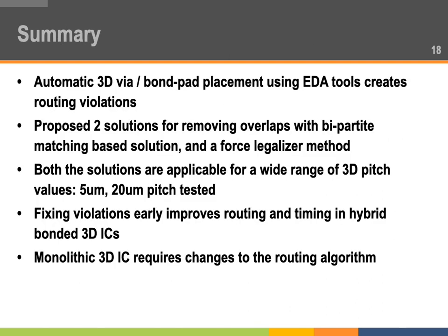In conclusion, we showed how a realistic 3D pitch value can cause various routing issues in different types of 3D ICs. We proposed a modified routing solution with two different legalization solutions for the vias, and we still make use of the EDI routing for improved timing and routability. The solutions, especially bipartite matching, are applicable over a wide range of design types and pitch values for 3D ICs, and show improvement to routability and the timing of the designs.